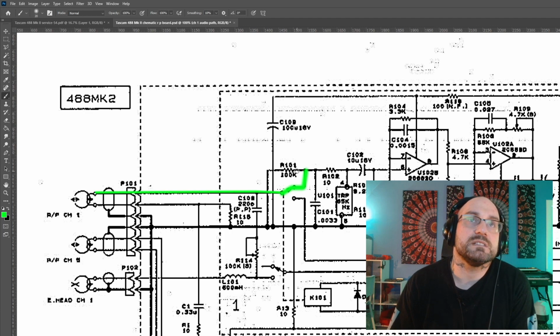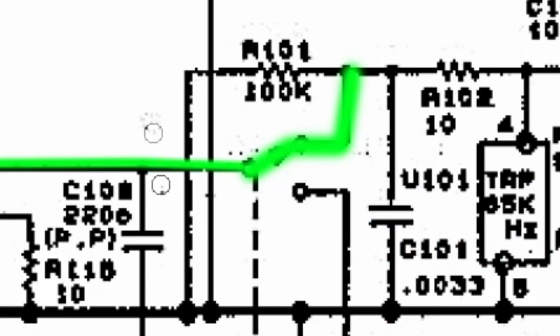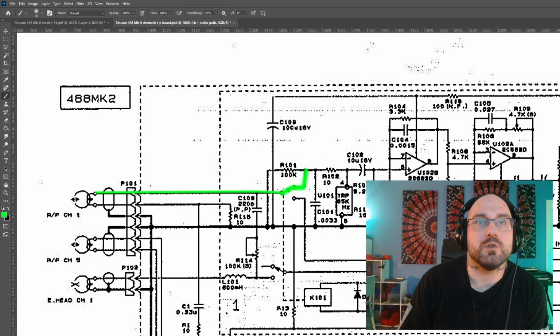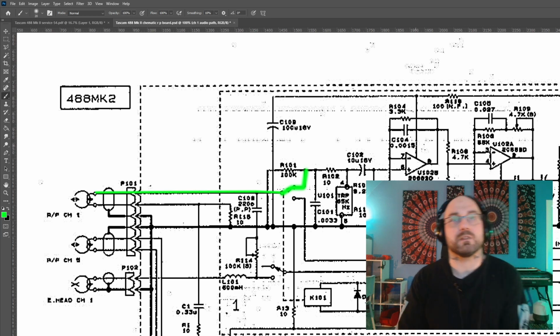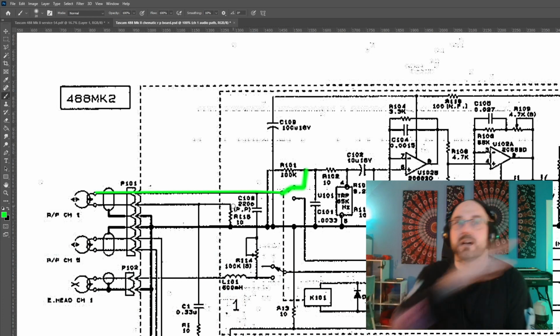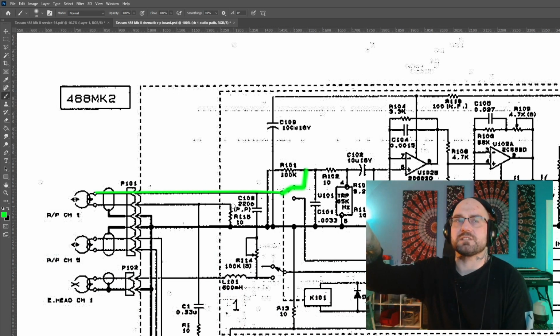And you can see that there's basically a kind of voltage divider here, and one end's going to ground. You can usually tell that these thicker lines, all of these things joining into one rail here, that's going to be ground. So it's definitely not going left. And like I was saying earlier in the video, these op-amps are almost like signposting on a path. So I know that the signal is definitely going in this direction. I mean, I'm pointing like this, but my image will be reversed on the screen presumably, but from the left of the schematic to the right.